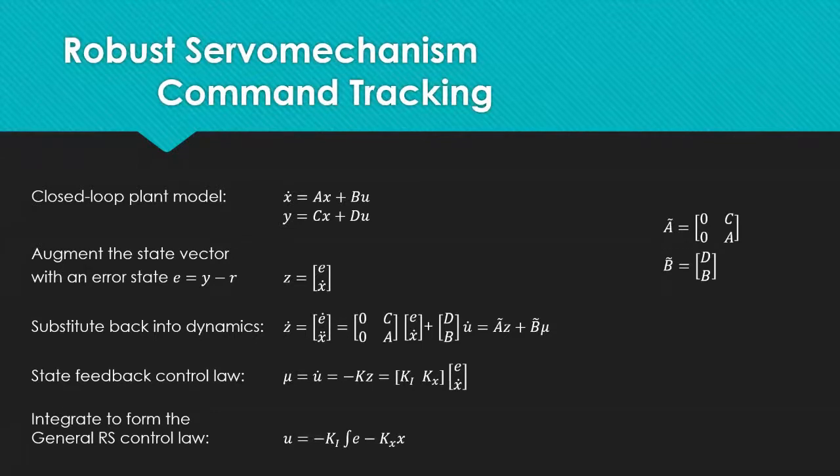Once the takeoff phase is completed and the controller is turned on, a robust control system is needed to accurately drive the UAV to the desired states. To properly track these commands, a Type 1 robust servomechanism scheme was implemented. This method forms the control problem in error space and regulates the error between the command and the estimated states to 0. The state vector for the UAV dynamics